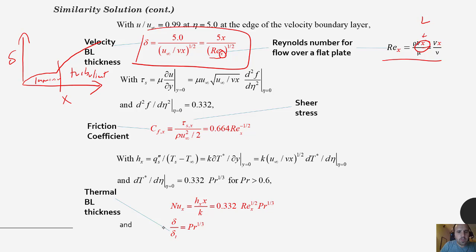If you remember, the Prandtl number was the ratio of momentum diffusivity to thermal diffusivity. So basically, if you have a higher momentum diffusivity resulting in a higher Prandtl number, that means your fluid is more viscous, and those viscous forces will be stronger, and your boundary layer will be thicker and thicker. If your fluid has a really high thermal conductivity or really high thermal diffusivity, which are going to be proportional to each other, then your thermal boundary layer thickness will be bigger and bigger, meaning the heat is propagating via conduction much faster than convection, which is caused by the bulk fluid motion.